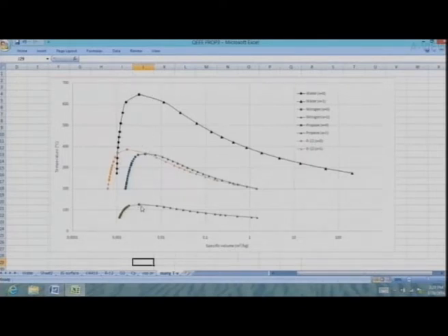Nitrogen goes everything below 126 Kelvin, oxygen will go below that, hydrogen will be even smaller than that. So they will all be like small domes over there. In between we get a lot of substances. Water comes here, and all of them have the same behavior, a very weak dependence on pressure on the saturated liquid side and fairly strong dependence on the saturated vapor side. But they all have the same general thing that I have been describing. So that's the important thing about this.